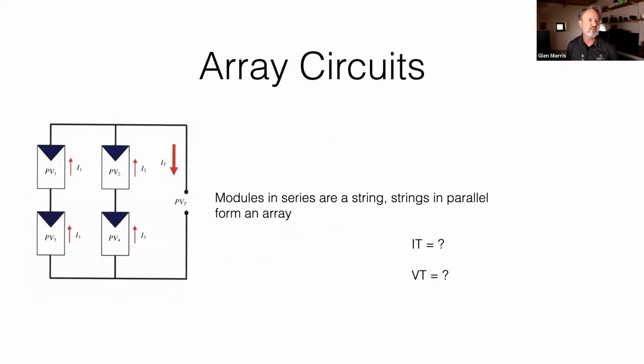So now we've got twice the voltage of one panel and twice the current of one panel by combining those. So using combinations of series and parallel allows you to hit the voltage requirements that you need to run a particular charge controller or inverter, and by paralleling to get the power levels up by increasing the current.